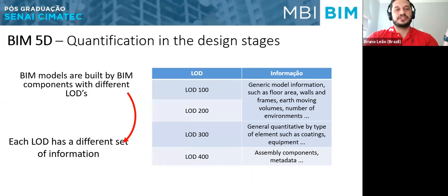When we talk about BIM 5D and quantification design stages, the first thought we have to have in mind is that BIM models are built by components with different LODs, or levels of development. Each LOD has a different set of information.